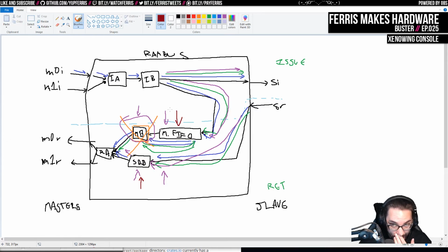Yeah, I actually think we need another FIFO here, and then I think the timing just works out. Then data comes into this FIFO a cycle early, but it's this issue here where when we read this, we can't request more data out of this FIFO until we read from it.